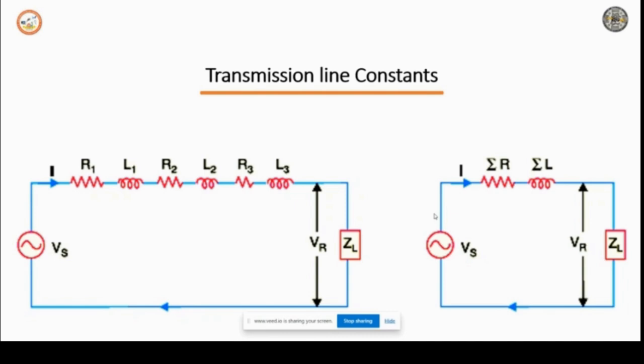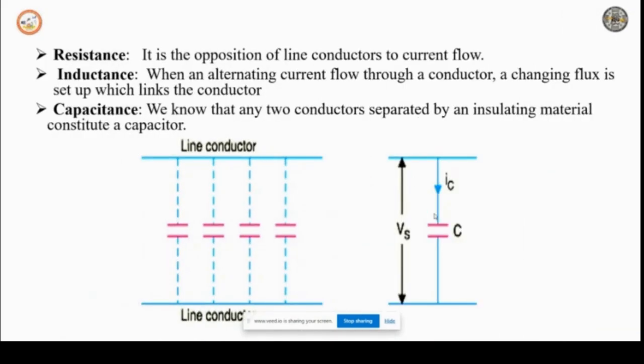You can see the next diagram. Now, the analysis of the circuit becomes very easy by lumping the parameters, as the same current is passing through each element of the resistance and inductance. Similarly, the circuits shown in the figure here, both A and B, are nothing but equivalent, as the same voltage is applied across each conductance and capacitance.